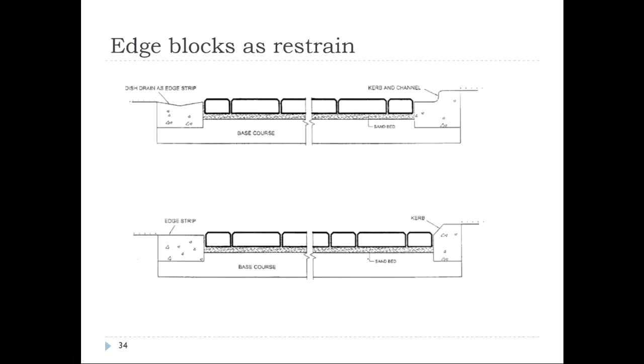And regarding this sand bed, whenever we are placing it above the compacted base courses, the construction of the lower layers is just similar to any other flexible pavement. You have to achieve the required densities. Now, when it comes to the bedding sand, you need to compact this bedding sand at a sufficient water content, which is identified as the optimum water content for this sand.